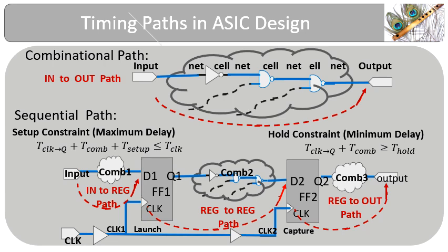In VLSI design, timing paths are the networks that are made up of the logic gates and interconnects that are enabled by the control signals. Each timing path is constrained by several parameters and is to be analyzed to ensure faithful data transfer. The paths, as shown in the figure, can be broadly classified as described below.